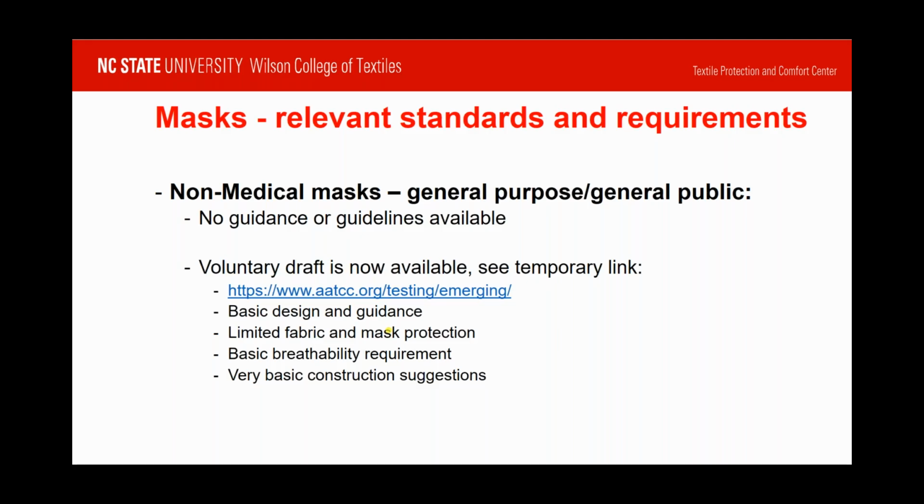It's a basic designing guidance, provides some very limited guidelines to measure fabric protection and some guidance on how you could think about mask protection, a breathability requirement. And here I should probably have changed that. It's formally a requirement on a limited breathing resistance. There's always confusion on the term breathability because people who only allow semi-permeable water vapor to go through also claim that to be breathable. Here we are really talking about fabrics that allow you to literally breathe through, which means they have a high air permeability and a low breathing resistance, which is very different.